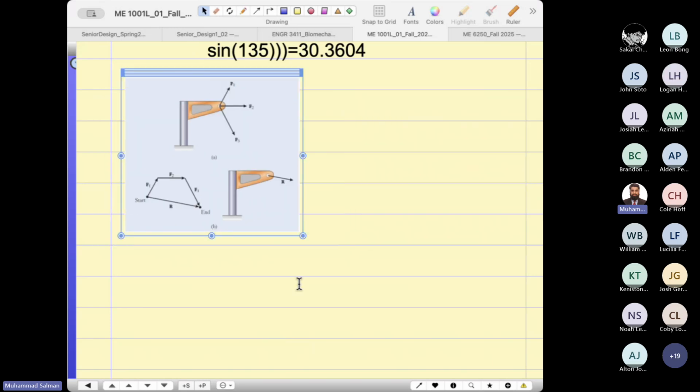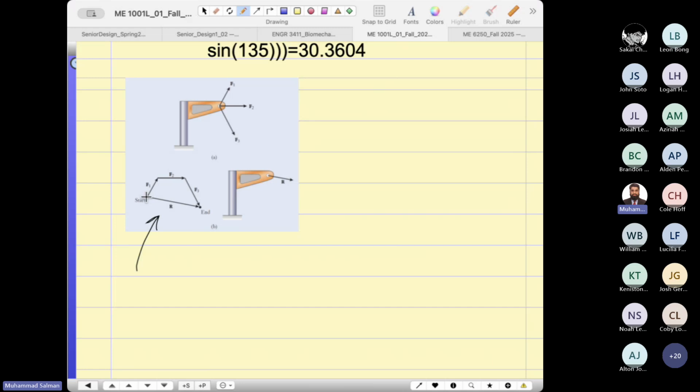It's not difficult. Look, the way you will do it, you will first of all draw this. I'm going to focus on this triangle. This is the resultant of these two forces, correct? Resultant one, and then this and this becomes one triangle. So now you will split up into triangle 1, triangle 2. That way you can easily find the unknowns one by one.